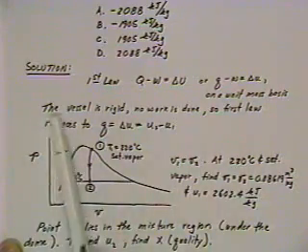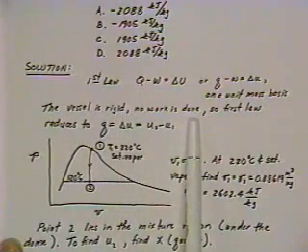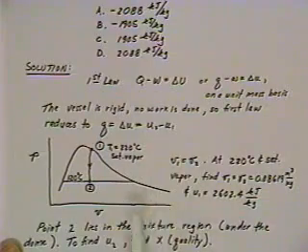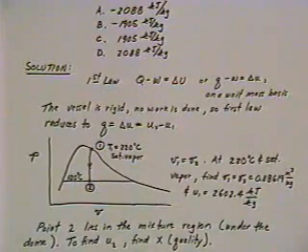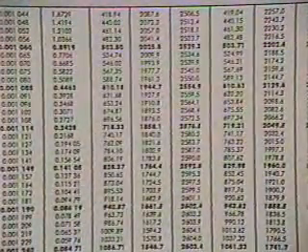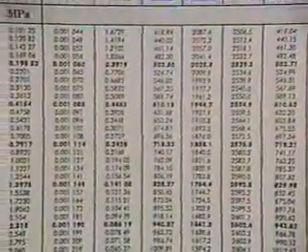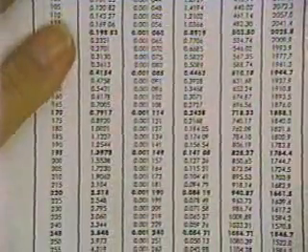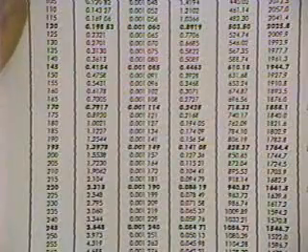Now, we also know that this is a rigid vessel. There's no change in volume, so no work is done. So the first law is Q is equal to delta U is equal to U2 minus U1. So we can now go to the saturated tables. You don't have this in your notes, but it's page 48 in the reference manual. So if we go to the reference manual, we can pick out some properties.